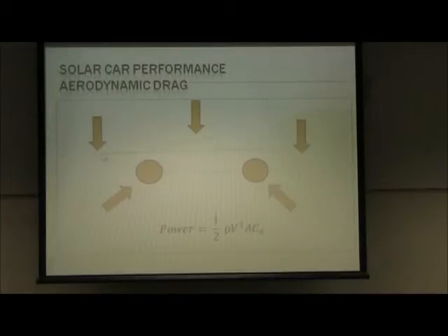Here at the end, what do you think this tail end should be like? Knife edge. As narrow as you can possibly make it. Okay, 1 centimeter, probably wider than you want it. Now why? Because when you go off a blunt end, what happens? Turbulence. You start getting these eddies, and what does that create? It's like a vacuum that's sucking you back.